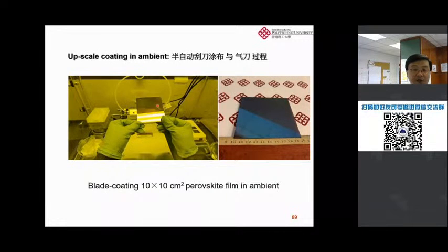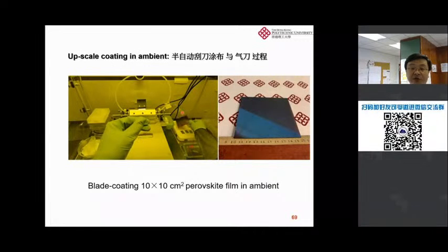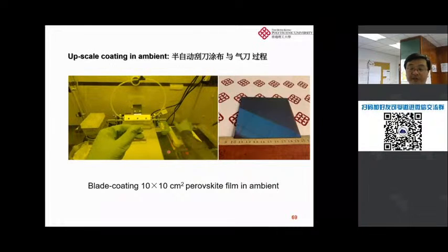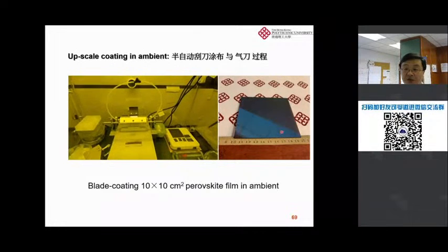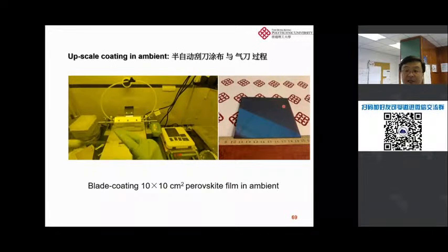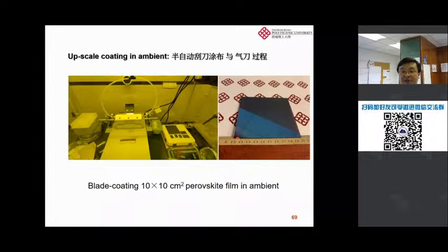This is a new process. The majority of the perovskite has already converted, but we still leave it on 110 degrees for a short period of time. And then that will give you a pretty uniform, shining film of perovskite. That's the thing that we want to do in printing. I think it's a nice demonstration that we are able to print perovskite solar cells.